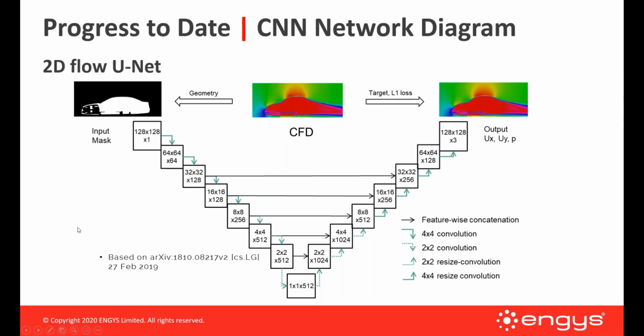to try and fit to the sampled velocity. So my input is the geometry, let's say, in the form of a binary mask, and my output is the velocity and pressure fields, and I can compute the error in my output versus the experimental, the CFD data that I've sampled to see how well or poorly my neural network is performing.